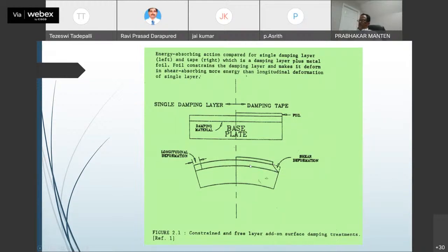So it allows all these elements to be sheared up to some point or all along. This constrained layer damping, as opposed to a free layer, provides a lot more energy dissipation for this vibrating structure to come down to zero very quickly.